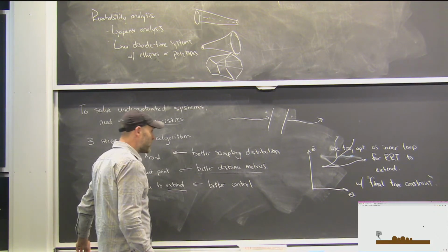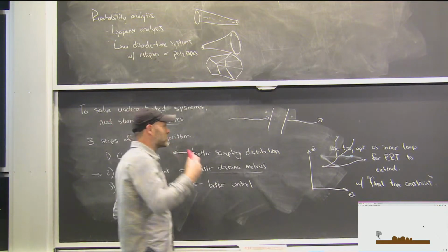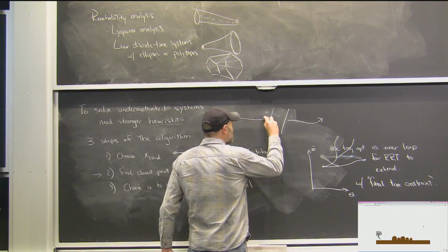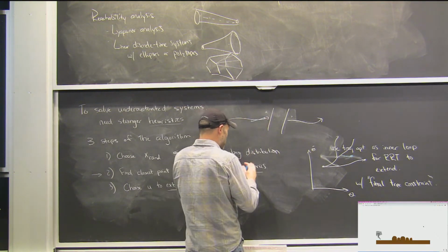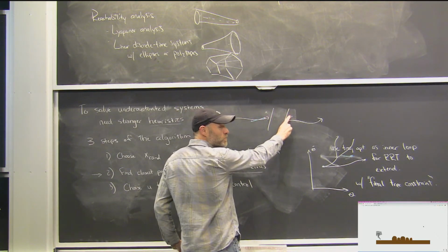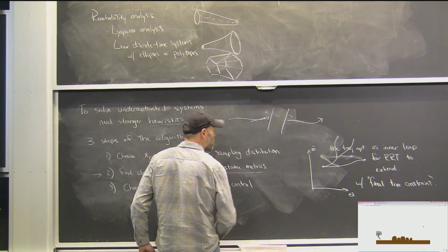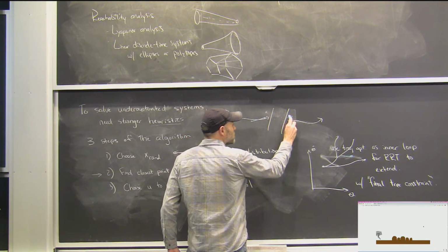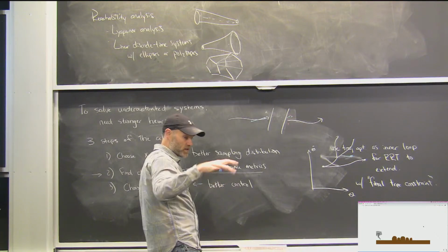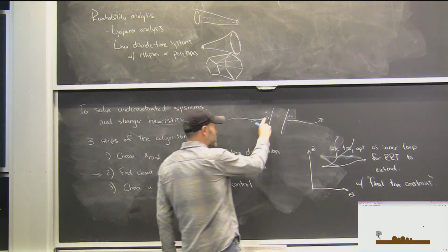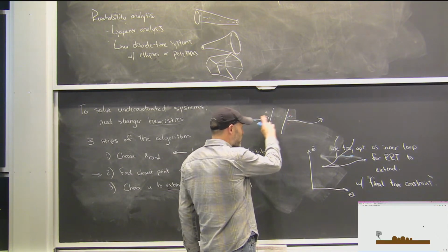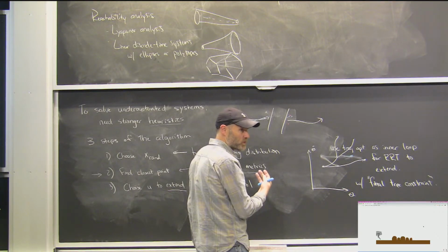If you can do reachability analysis through there, for instance, the very simple version I just showed, right? If I had a point here, blue, on my original tree, and I cast some red points across, knowing that I'm close to this red point would actually tell me to project a blue point through the wormhole, and can solve some of these challenges in hybrid systems. That's why it worked. The little dog robot hopping was a hybrid system, and that reachability-based algorithm did work through hybrid systems in that way. Trajectory optimization can go through the hybrid systems in the way we like.